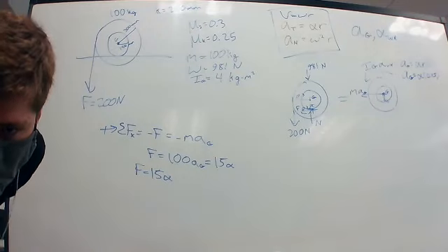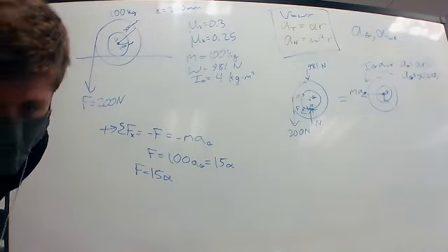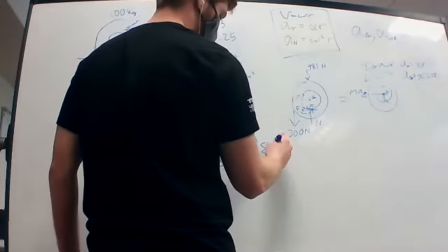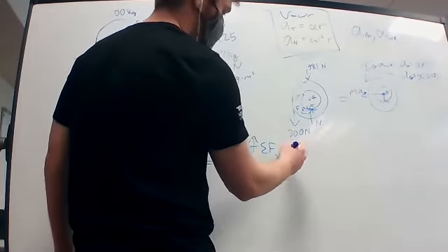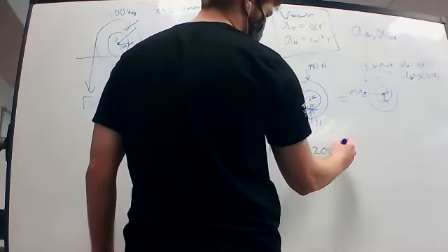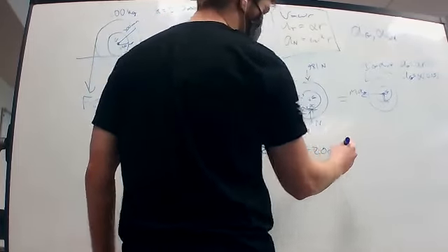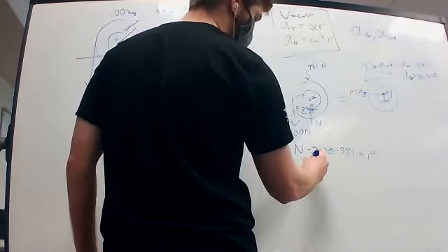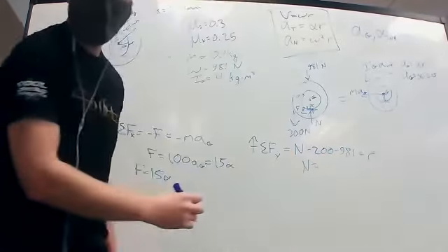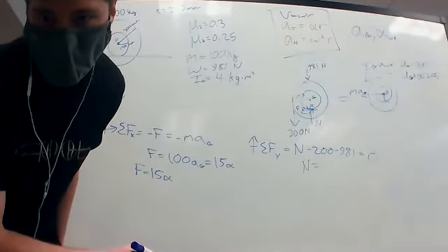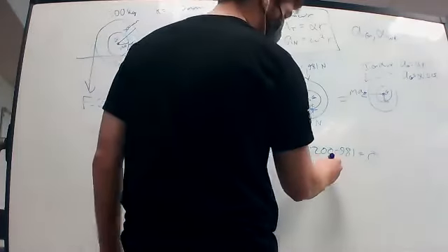And then they do the sum of the forces in Y. So that's going to be normal force minus 200 minus 981 equal to 0. So normal force is 1,181.